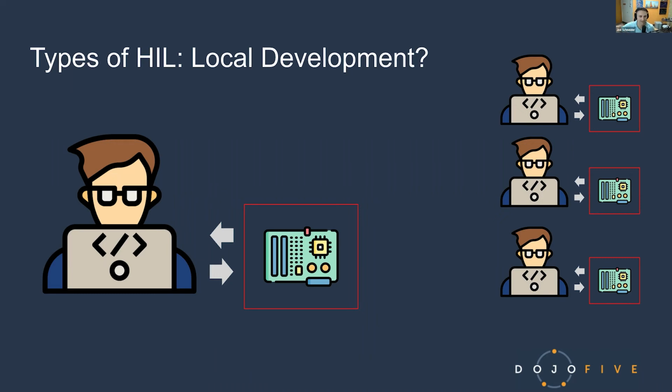So hardware is gating development, and usually getting the graphics library up and getting your elements on the screen is something you want to do fairly early, because there's a lot to do on top of that. It's a foundational piece that you want to get in place. So I think that is another best practice I've seen, where people compile for their desktop machines and abstract out the display. And a lot of times you have to abstract out some of the simulation hardware.